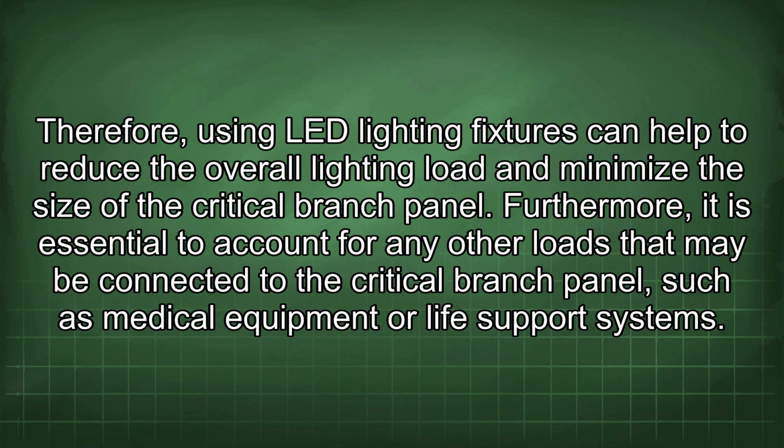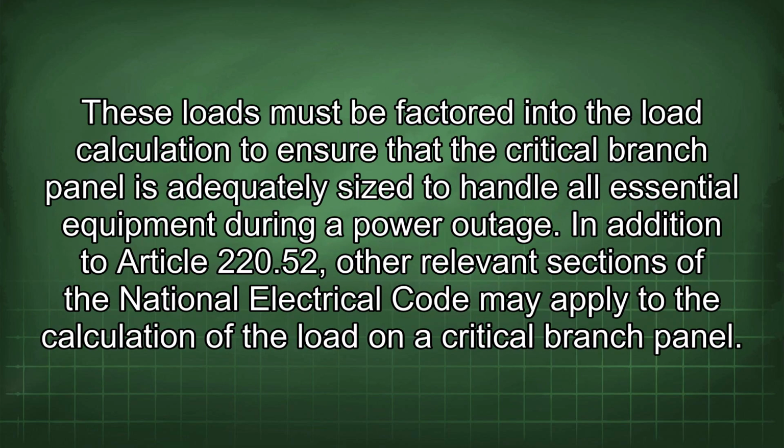Furthermore, it is essential to account for any other loads that may be connected to the critical branch panel, such as medical equipment or life support systems. These loads must be factored into the load calculation to ensure that the critical branch panel is adequately sized to handle all essential equipment during a power outage.